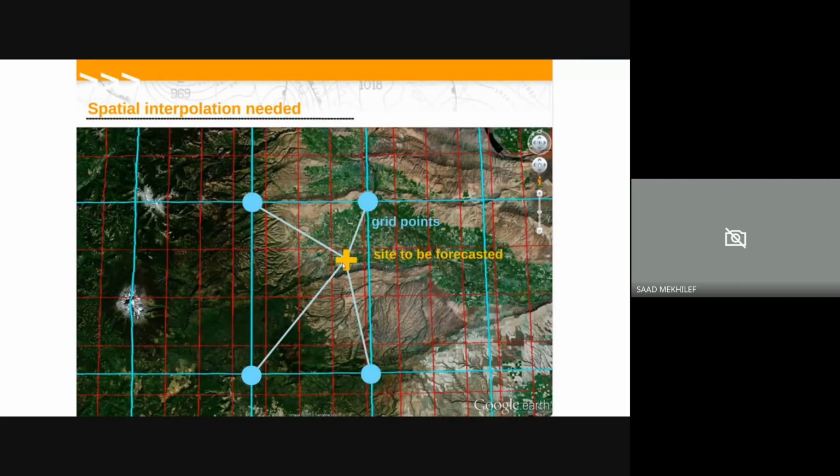If it's far from the load center, that's fine. But is it very far from the grid connection point? If yes, how much does it cost to do grid extension to that location? If it is too expensive, then just forget about it, because grid extension is quite expensive. That's why we start surveying with these parameters: load centers and the grid connection. That's very, very important.